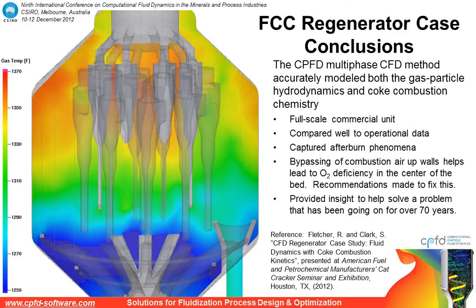It captured the afterburn phenomenon and suggested that bypassing of the combustion air up the walls was contributory to the afterburning. The important thing I'd like to point out is that this problem has been present in this unit for 70 years, and a lot of suggestions have been put forward as to things that might be causing it, but this CFD simulation provided a lot of additional insight which will almost certainly result in engineered solutions to mitigate, if not eliminate, the afterburning in this unit.